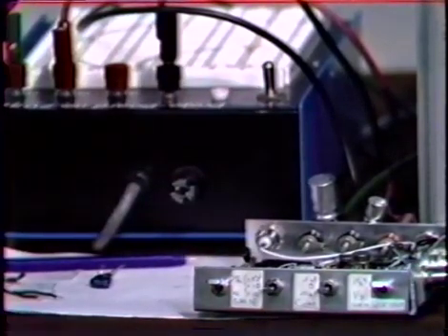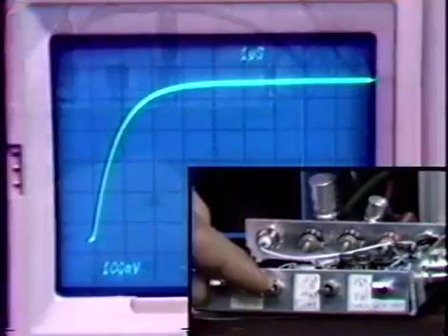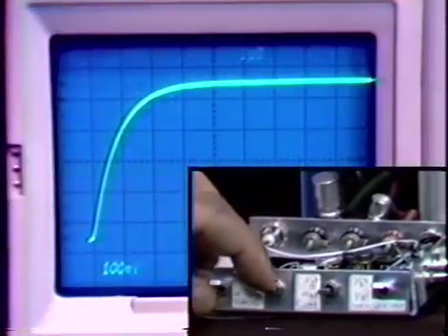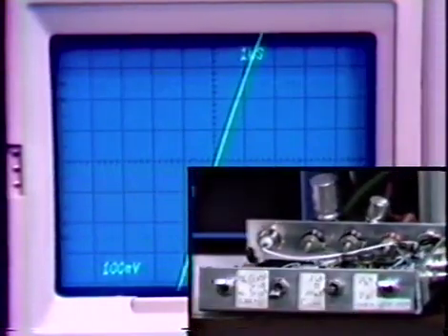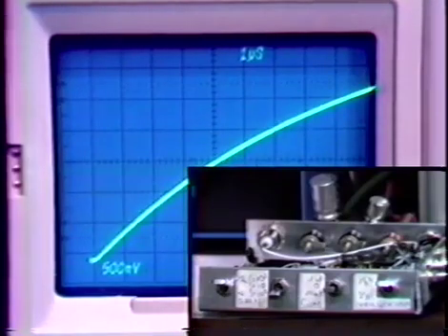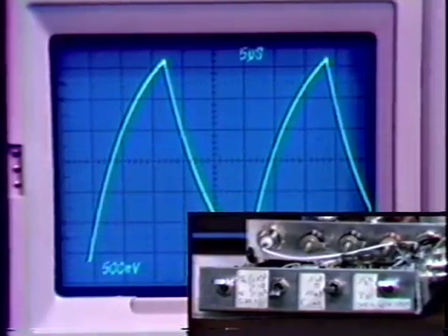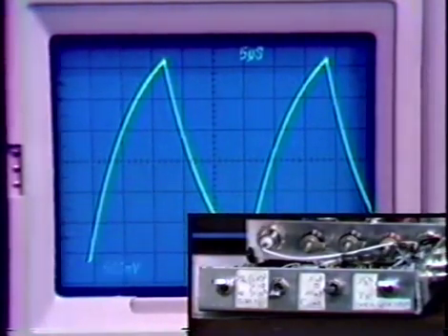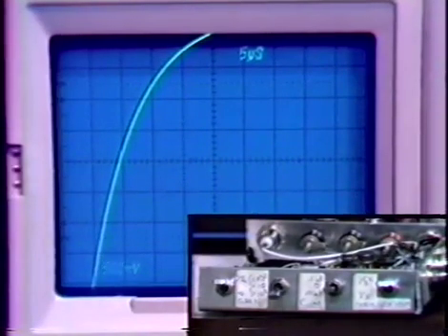And now up the gain by another factor of 10. If I throw this switch down, we get a closed loop gain of 100. We make f 1/100th. Let me do that. And again, I have to change the vertical scale on the oscilloscope. We find out now the bandwidth is so deteriorated with the original value for the capacitor that we have to slow the signal generator. So let me do that so that we reach final value.